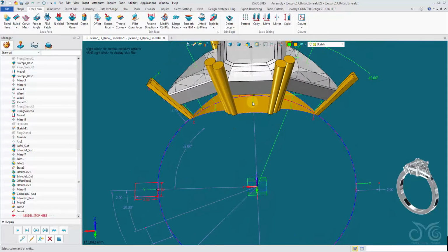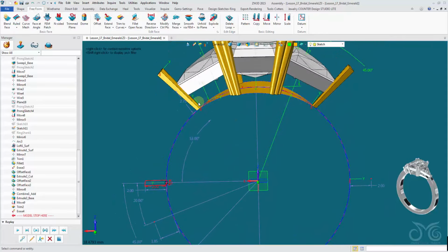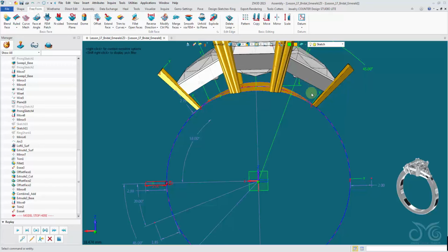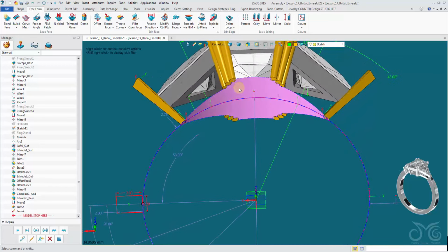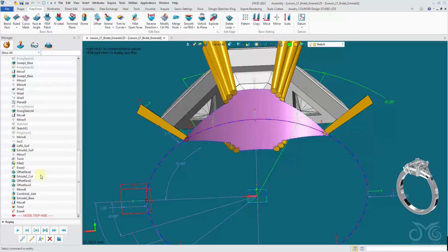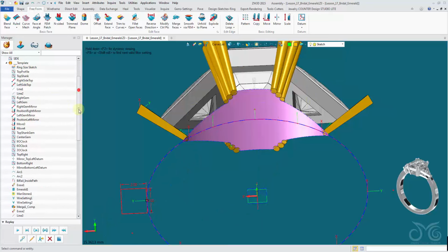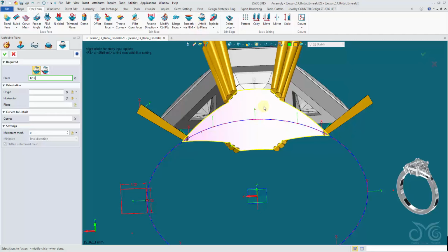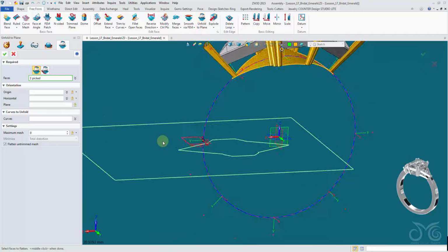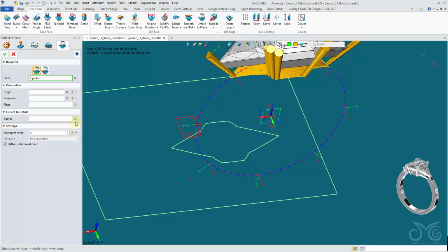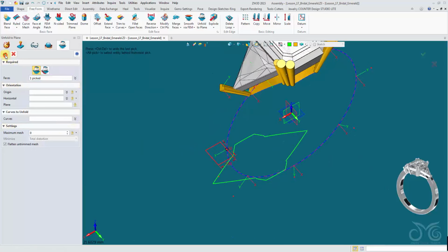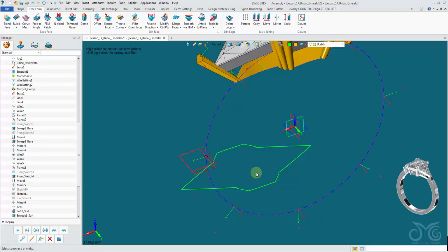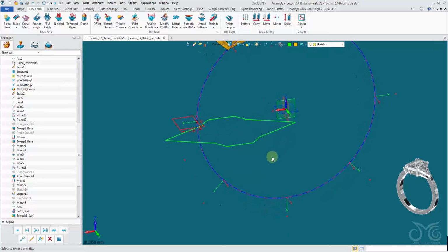Okay, so here is our plate. We could shell this to create the plate and be done with it. In this case I want to create piercework in here for this undercarriage. Okay, so the way I do this, we've seen before, I like to unfold this face to a plane. Okay, let's say default plane is good. Confirm. Okay, so I'm going to create the piercework on this plane and then refold it.